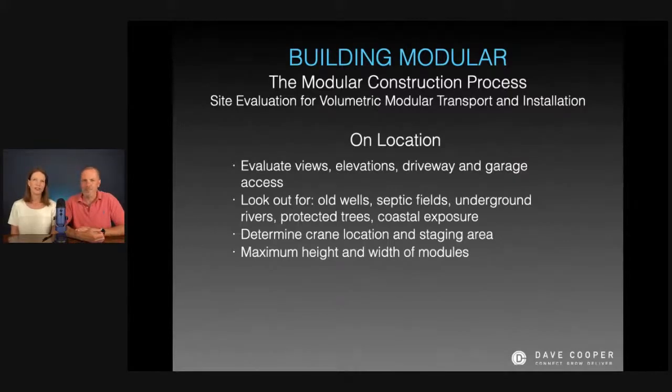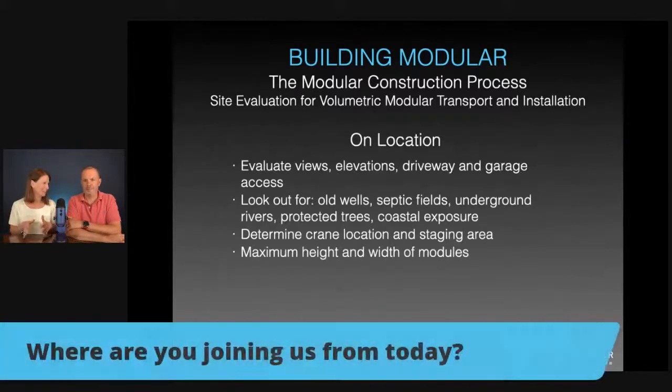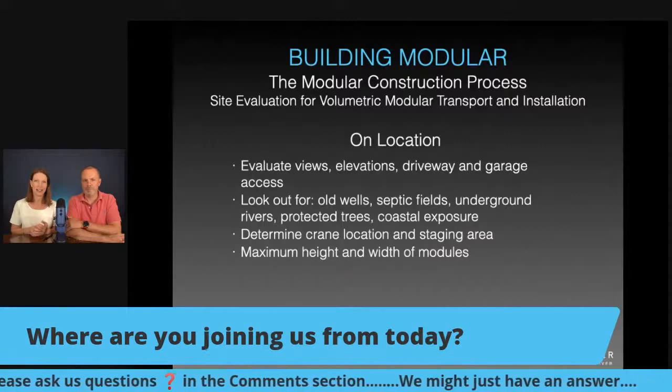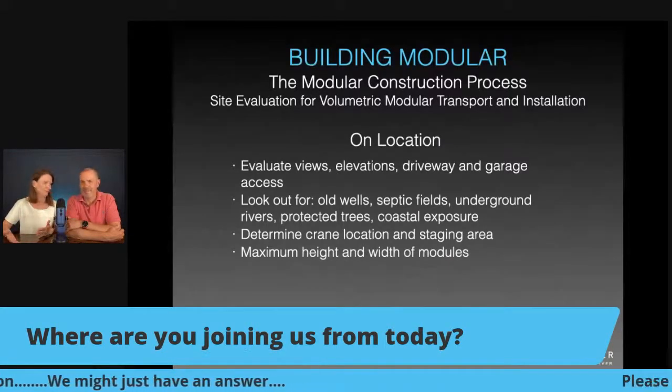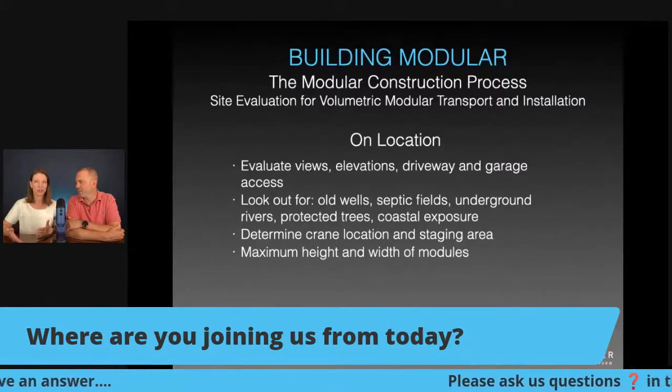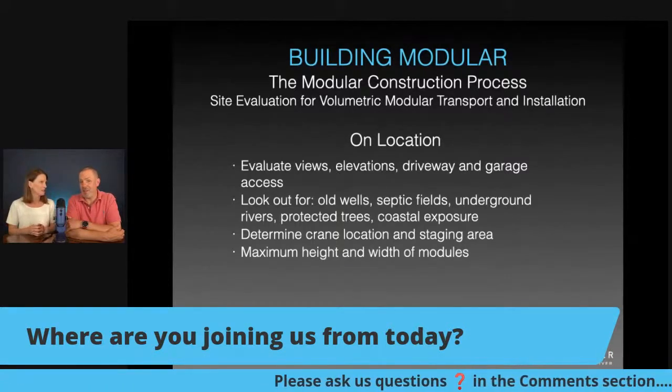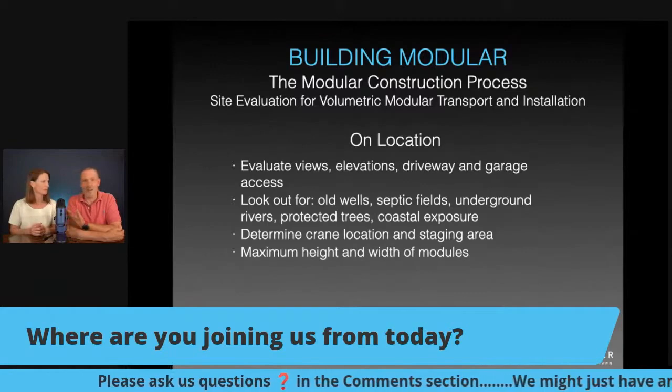Yeah. These are some lessons that we've heard people learn the hard way. Going back to some projects we've worked on, the land was abandoned and we didn't know that there was a pre-existing structure there. Whoever had torn it down just literally dug a hole and left the old house there. When we went to dig the foundation, we discovered an old home buried in the ground. So these are things you need to look out for. And you've got to get rid of all that stuff. That's what they used to do, they used to bury their garbage.